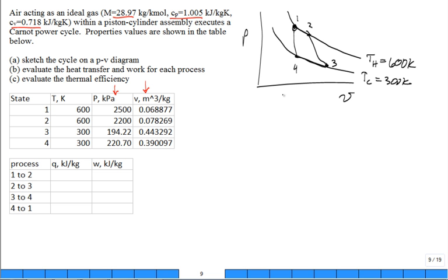But there's the diagram. You're bringing in heat right here, Q at the high temperature, rejecting heat from the cycle, Q at the low temperature. They put these little dash marks like that to indicate what for the process 2 to 3 and 1 to 4? Adiabatic, no heat transfer, as if that's insulated. There's a little sign in engineering for insulation, right? Okay. So we sketched it on a PV diagram.